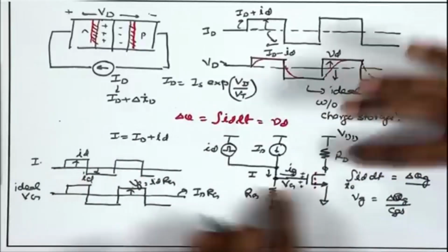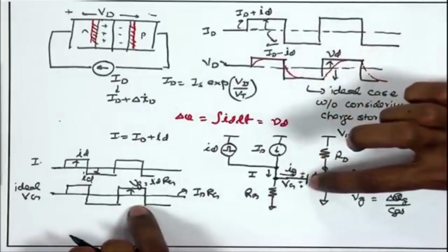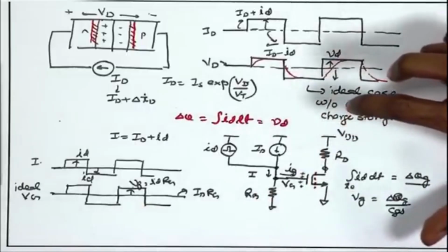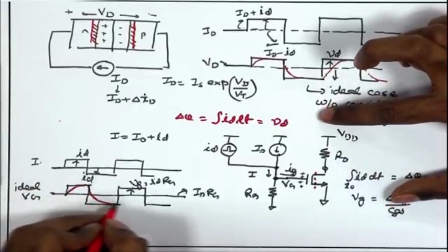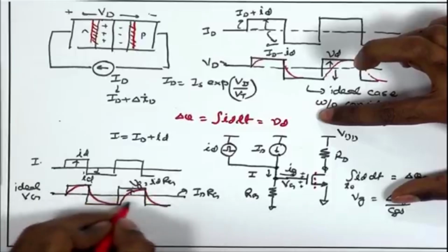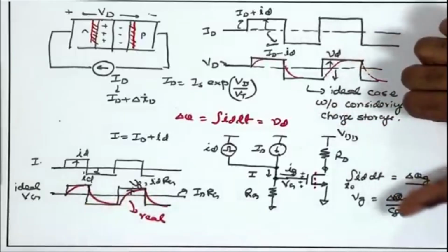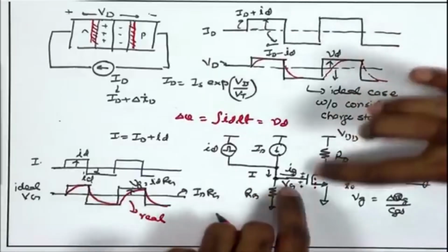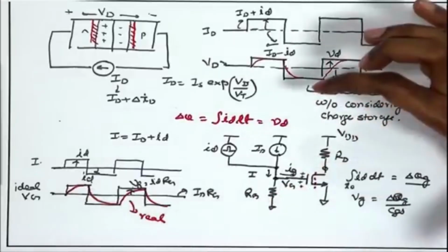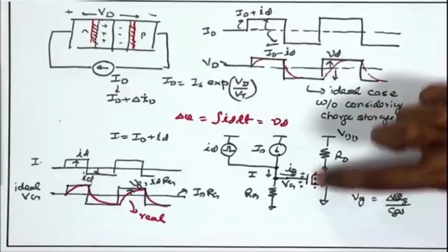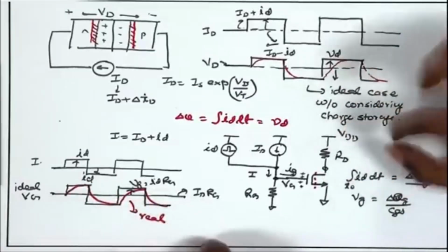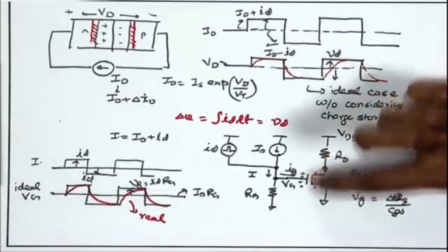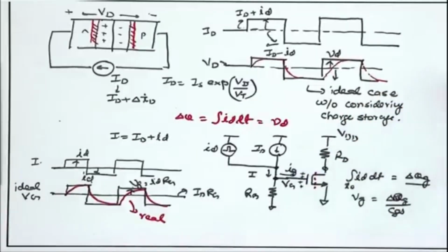Now, that means that once again rather than this voltage going instantaneously up and down, it will take a finite amount of time to rise and fall. So, this is the real characteristics, right. Once again, because of this charge storage mechanism, we are not able to change this voltage instantaneously, likewise we are not able to change the channel charge instantaneously. It will respond after a delay, when you have been able to integrate the required amount of additional charge to produce the new VGS across the MOSFET, that is between the gate and the source.